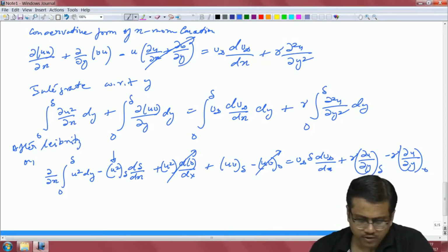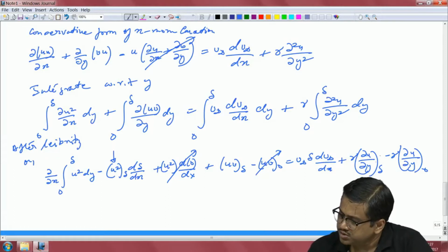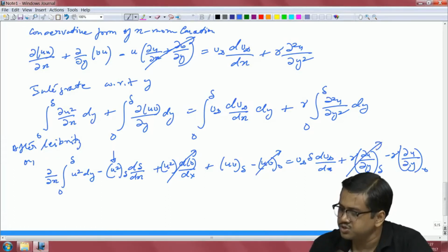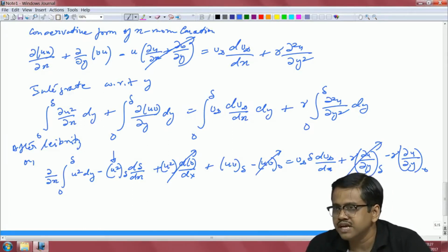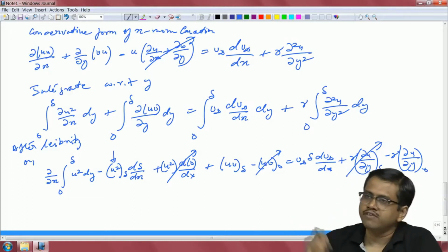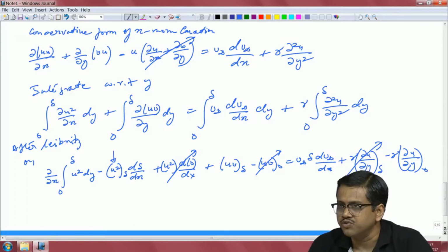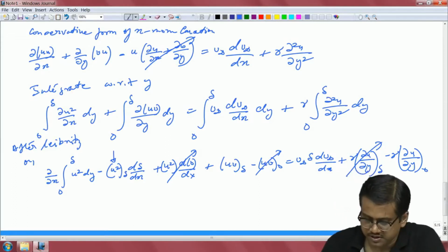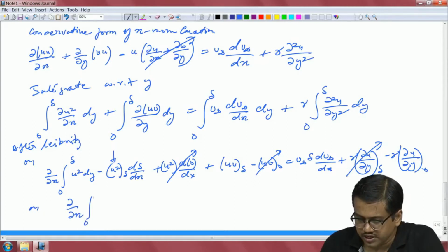Okay. And of course, on the other hand, if you go to this side of the equation, you will find that what about the nature of this, should this go to 0 as well, because you are looking at the shear stress at the edge of the boundary layer, where the velocity should have actually become equal to u infinity. Okay. All that gradient is very small, that is what we are arguing. So, therefore, we can write this equation in a nicer form.